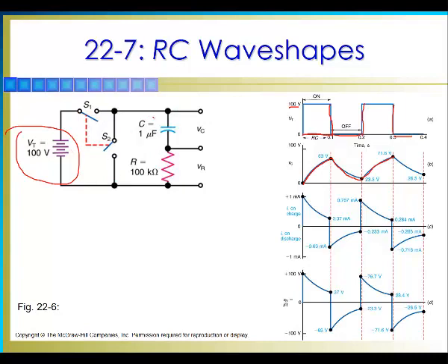As the capacitor charges, the current starts decreasing from the 1 amp. It will go down 63% because the time the switch is on is only one time constant. Then the switch here will open, and this one will close.